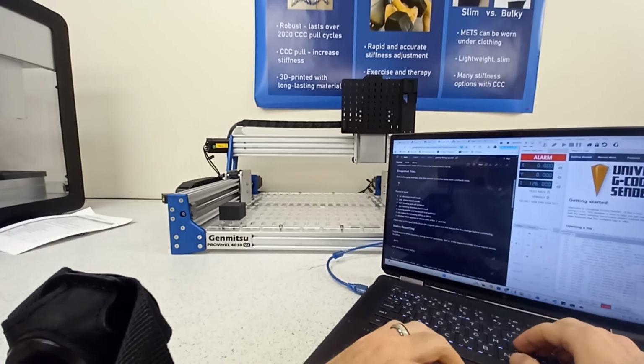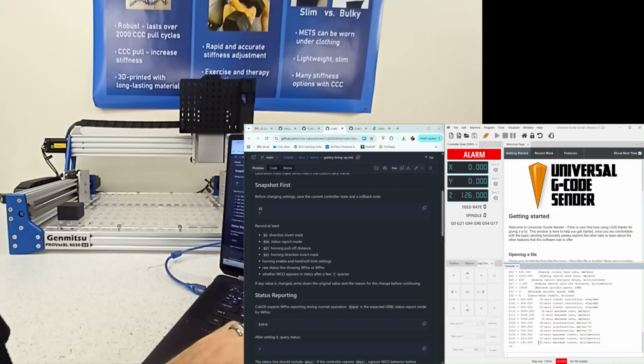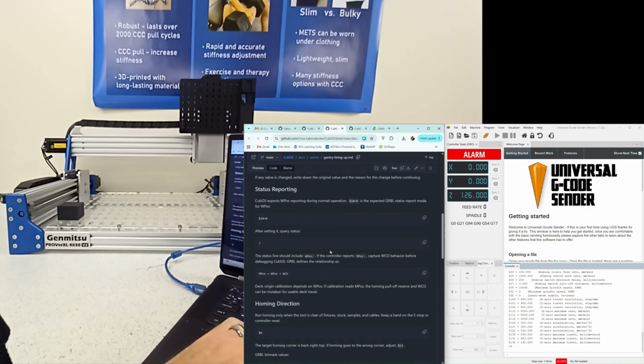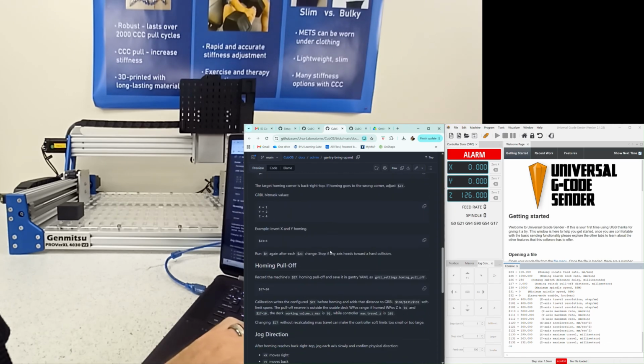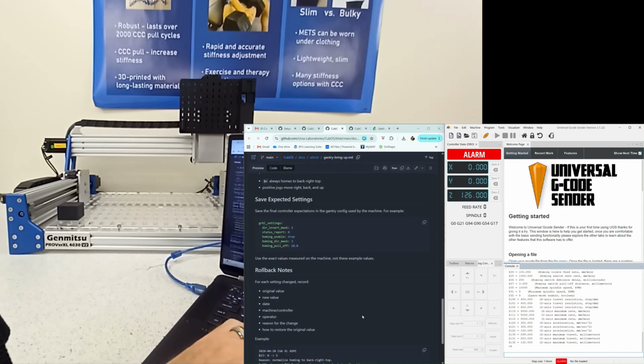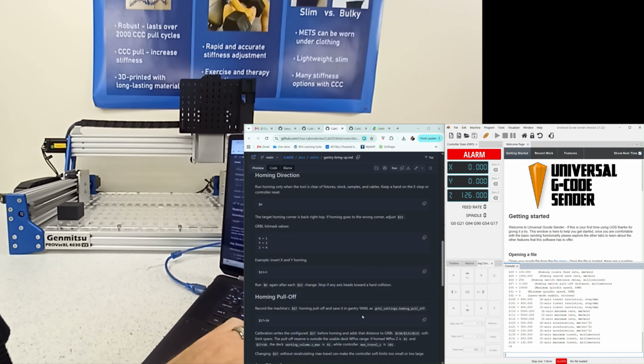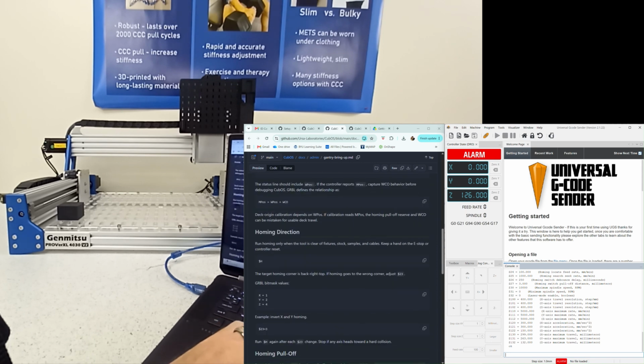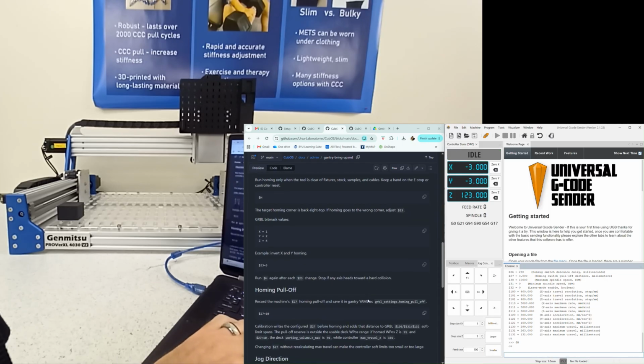Okay, looks like this is where we are. Let's record these things. I already have them recorded here. Okay, let's see what it does. Let's make sure the homing direction is correct. The machine is already in the right corner, so let's do a few jogs.